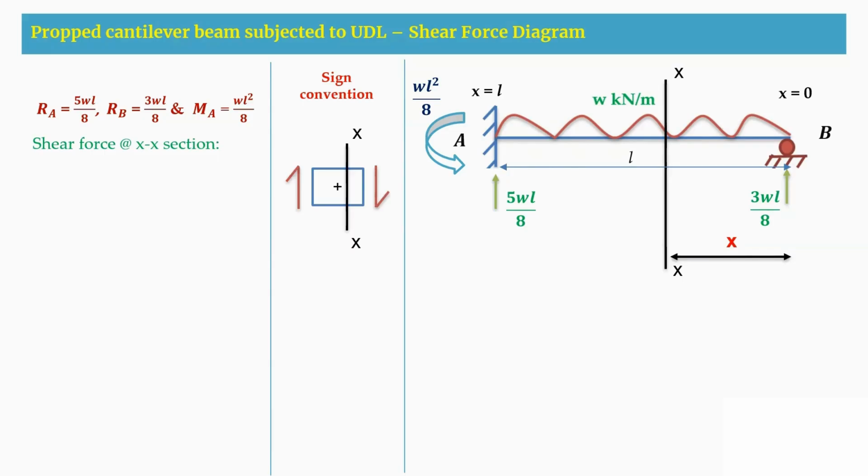So that is your positive shear. Now when we take the same element and cut a section, towards your left hand side and towards your right hand side about the section, if you are having the shear in anti-clockwise direction, you can see here, this is in the anti-clockwise direction. Then the shear we are going to consider as a negative shear. So this is a sign convention.